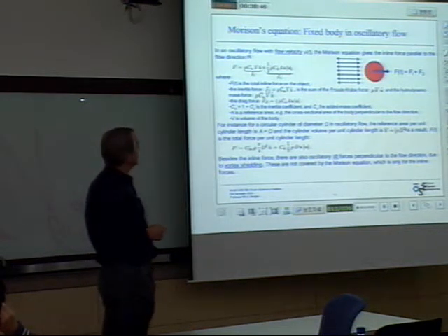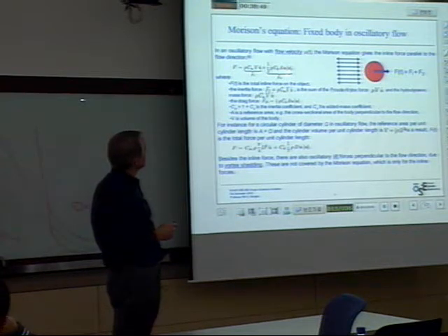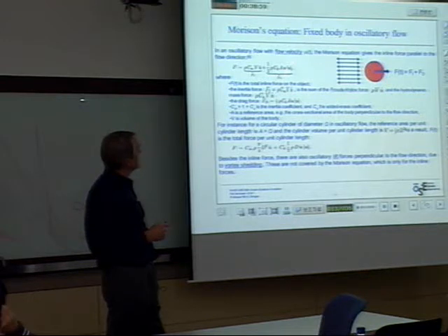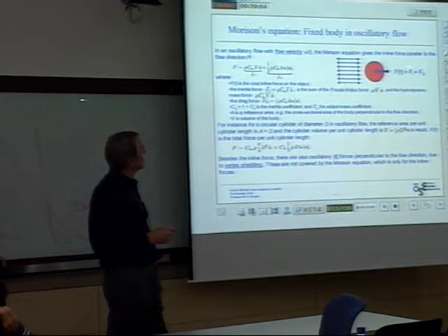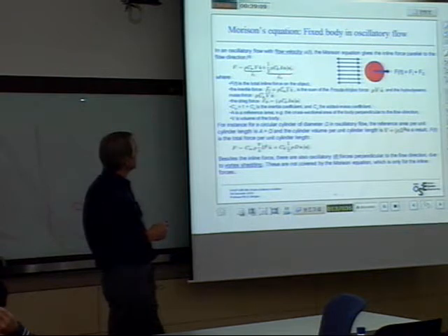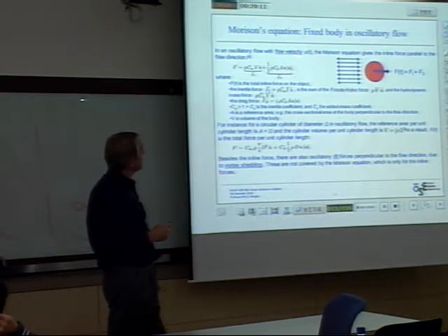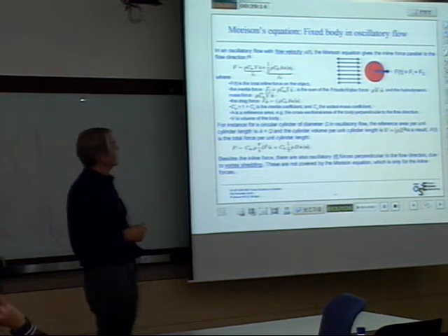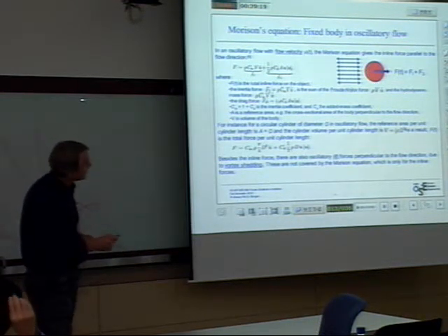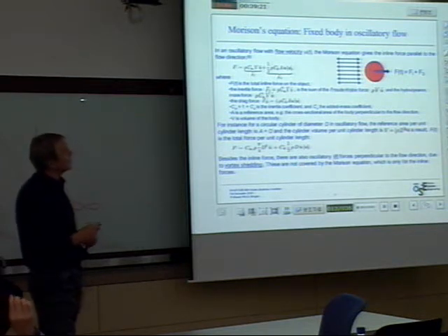velocity, what do you call it? The absolute value of the velocity. So this term changes direction depending on which direction the flow goes. You may have to use a little bit more time to understand this, but it is a drag term that is proportional to velocity square, and it is always pointing in the direction of the fluid motion.